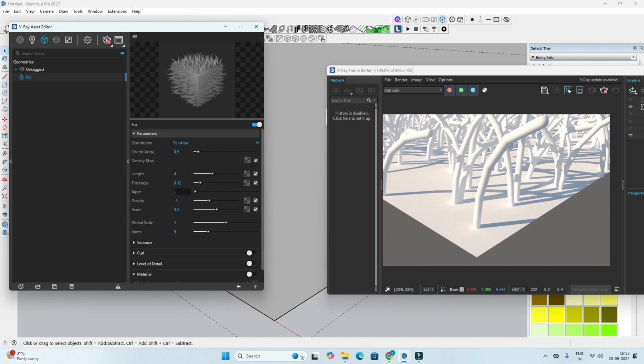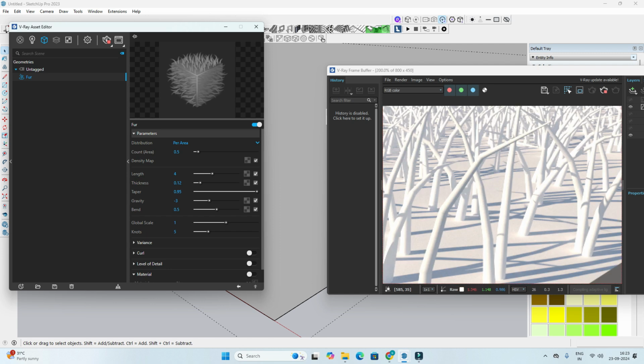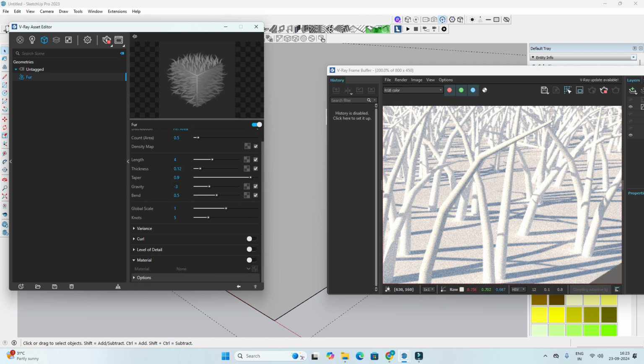Now most of the time I'll give this one 0.85, 0.9 or 0.95. It completely depends on the situation. If you are creating a grass material, maybe you can go for 0 also, no problem. Or if you are applying a mat or rug, a floor rug and all, then in that situation we can apply maybe 0.3, 0.4, something like that. Okay, right now I'm giving this one 0.9.